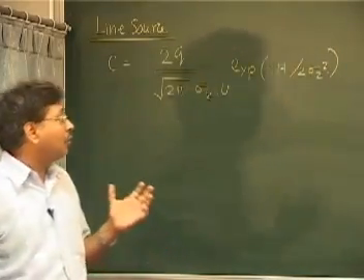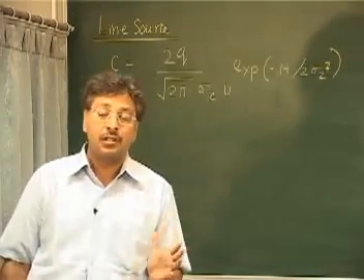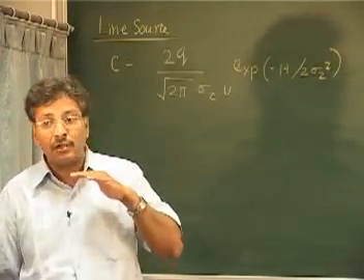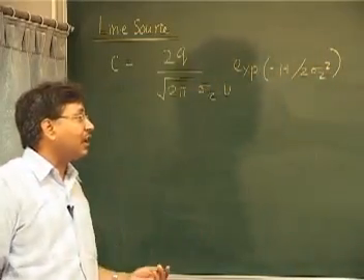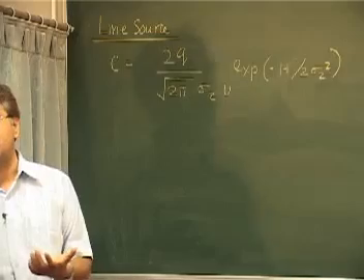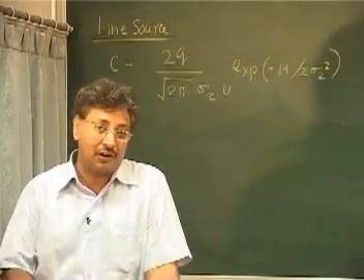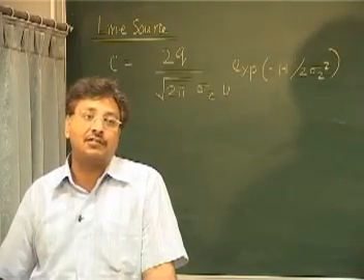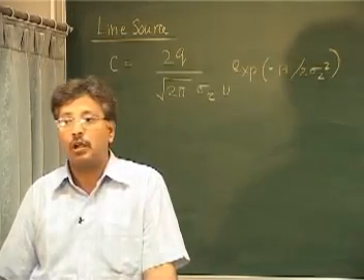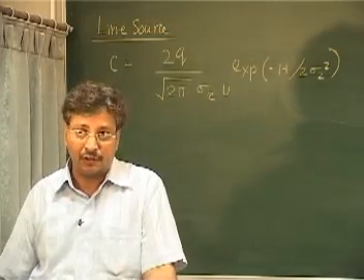There are situations where we cannot apply the model, because these models are based on certain assumptions, and one of the important assumptions is that the terrain is flat, okay. If the terrain is not flat and has its own complexities, then we go to physical modeling. We are not discussing that in this course, but wind tunnels are very extensively used to understand dispersion under complex conditions, okay.